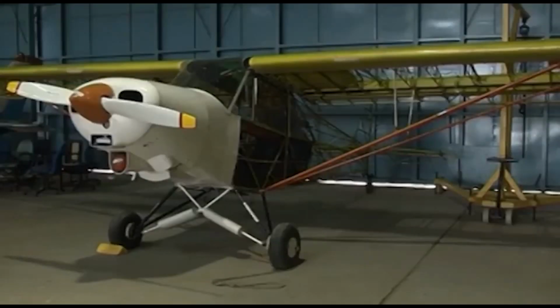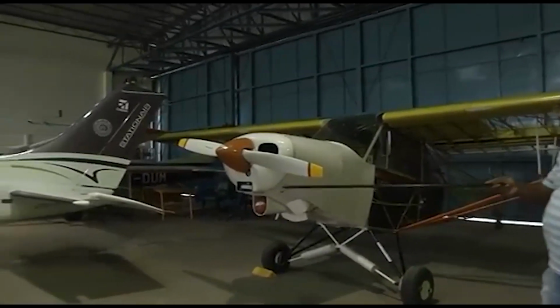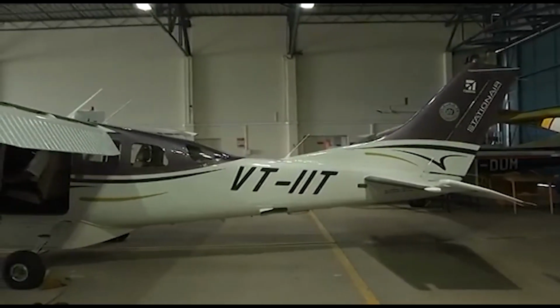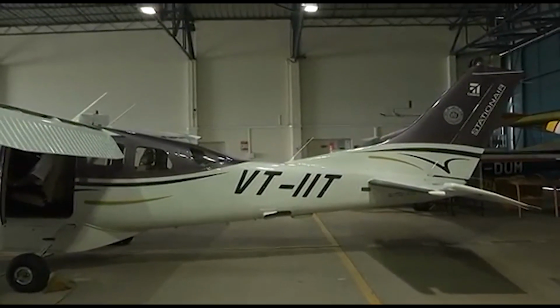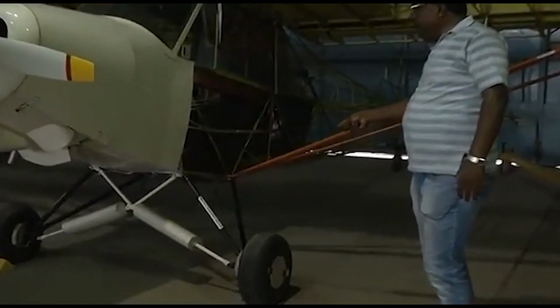Before I end, I want to stress another point as far as the landing gear is concerned. Remember, for all this tricycle landing gear, we have understood why the CG should be a little ahead of the landing gear. Otherwise, the tail will hit the ground. But for a tail dragger, the CG is behind the landing gear.